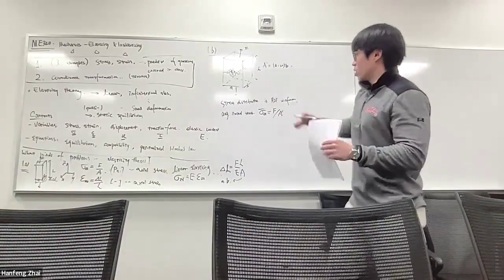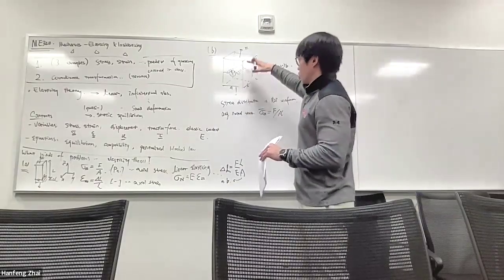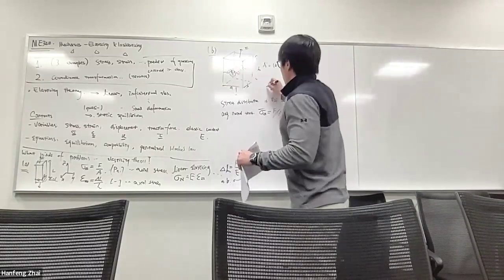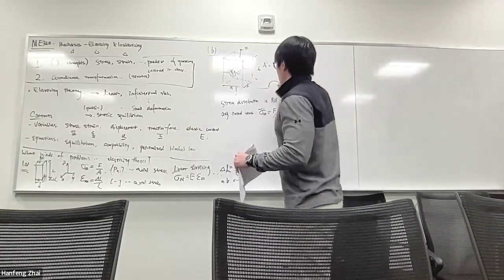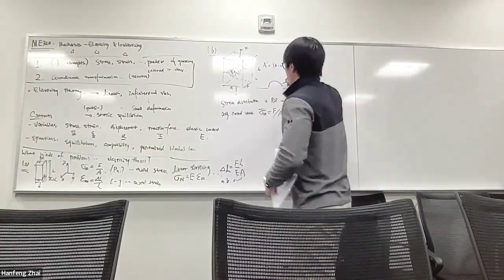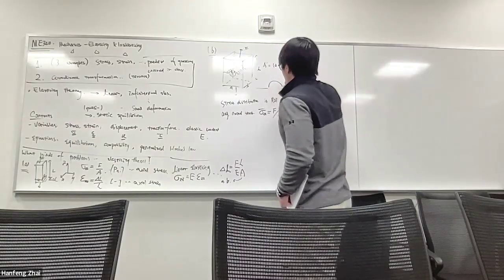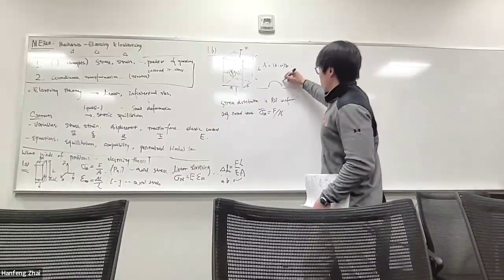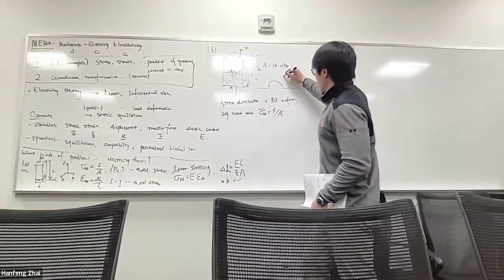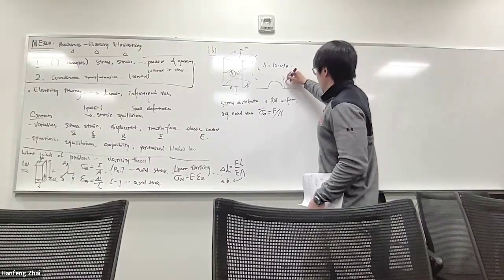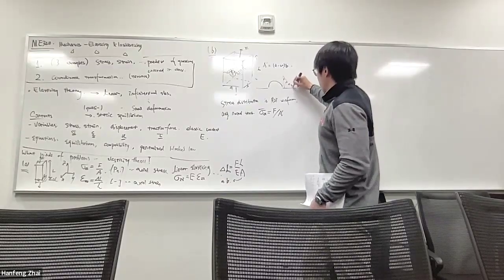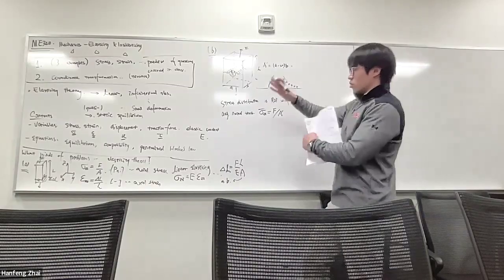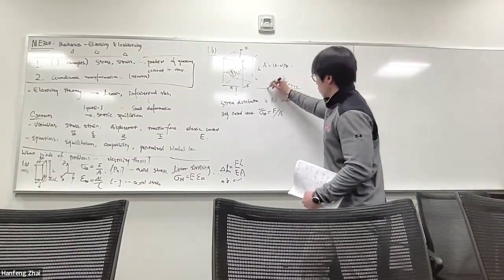And since we know there's a stress distribution difference, there's a stress field around the hole, we know that the stress distribution around this spherical hole, or cylindrical hole, the stress sigma ZZ will be much higher around the hole, and it gradually decays as it's further away from the geometric hole we introduced.